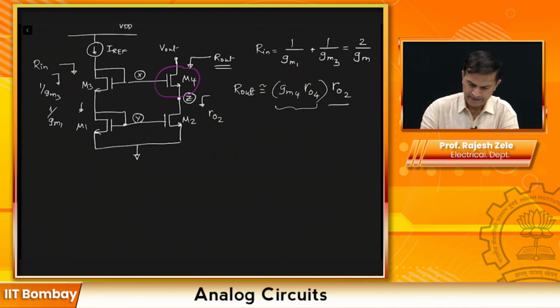Now let's analyze what's the lowest output voltage Vout that you can tolerate, so that both the transistors M2 and M4 are in saturation. Okay, so I'll mislead you first. A typical answer could be, hey, it could be just VDSat2 plus VDSat4. That would be your shoot from the hip answer, right? So you would think that the minimum Vout can be VDSat2 plus VDSat4, which is approximately 2 VDSat.